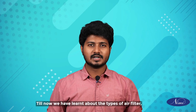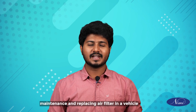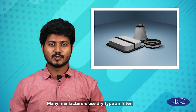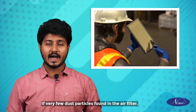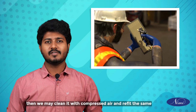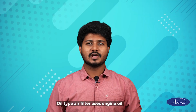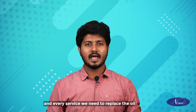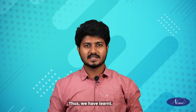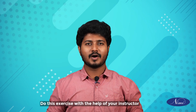Till now, we have learned about the types of air filter, maintenance and replacing the air filter in a vehicle. Many manufacturers use dry type air filters in which we can replace the filter easily. If very few dust particles are found in the air filter, then we may clean it with compressed air and refit the same. An oil type air filter uses engine oil, and at every service we need to replace the oil and clean the wire mesh. Thus, we have learned. Hope you are clear on this. Do this exercise with the help of your instructor.